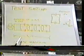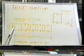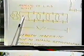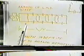Okay, our test setup again. We've taken our element and rotated it 90 degrees to give us longitudinal rather than transverse flow. But of course, still using the same components in the element. We have our same amplifier oscillator arrangement. The amplifier is producing about the same amount of power as before, but now our distributed line looks like this. And it's a quarter wavelength long, meaning that we have our low impedance, high impedance.